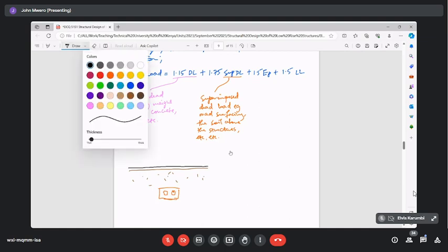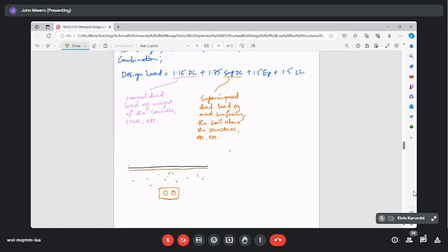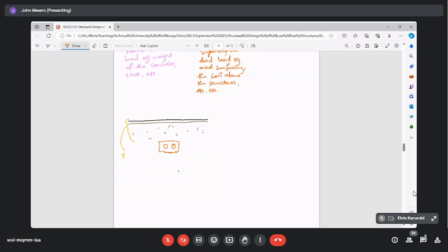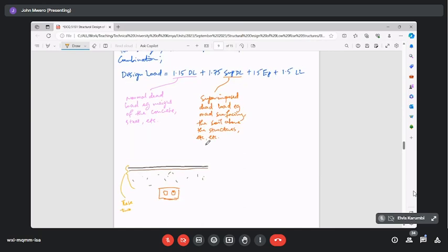These two are likely to change significantly during the service life of the structure. Because every few years, we put a new road surface. We resurface the road. So easily, we started with a surfacing of 50 millimeters. In the next maybe 20 years, you find that the surfacing existing there is maybe 3-4 times that.